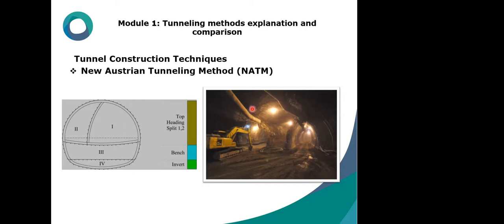Soil mass around the lining of the tunnel contributes to load bearing and helps to withstand the loads. So total overburden loads won't be sustained by the tunnel lining due to arching. This phenomenon will be extensively discussed in the relevant section during the diploma. Also, this method is economical and flexible for different kinds of situations.